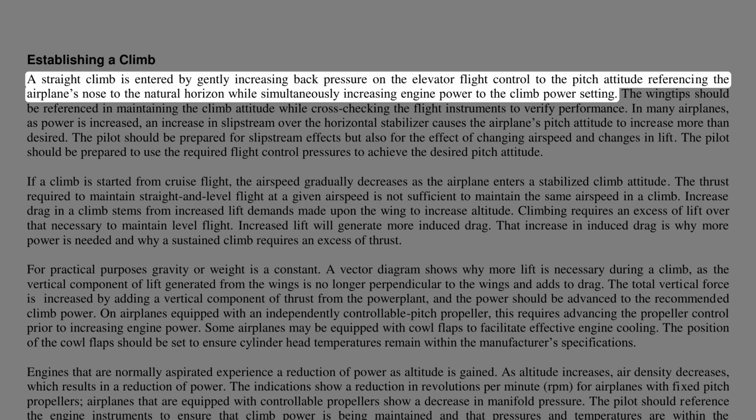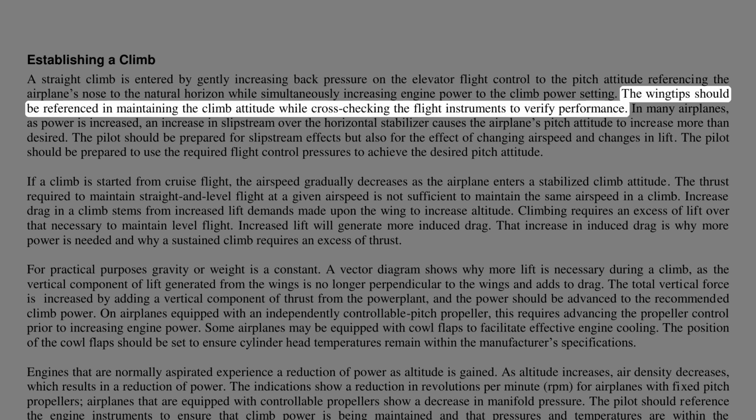A straight climb is entered by gently increasing back pressure on the elevator flight control to the pitch attitude, referencing the airplane's nose to the natural horizon while simultaneously increasing engine power to the climb power setting. The wingtips should be referenced in maintaining the climb attitude while cross-checking the flight instruments to verify performance.